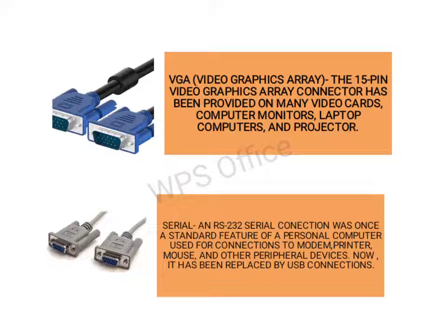The 15-pin Video Graphics Array has its functions. Number 1 is red video, 2 green video, 3 blue video, 4 monitor ID 2, 5 TTL ground monitor self test, 6 red analog ground, 7 green analog ground, 8 blue analog ground, 9 key flag hole, 10 sync ground, 11 monitor ID 0, 12 monitor ID 1, 13 horizontal sync, 14 vertical sync, and 15 is monitor ID 3.